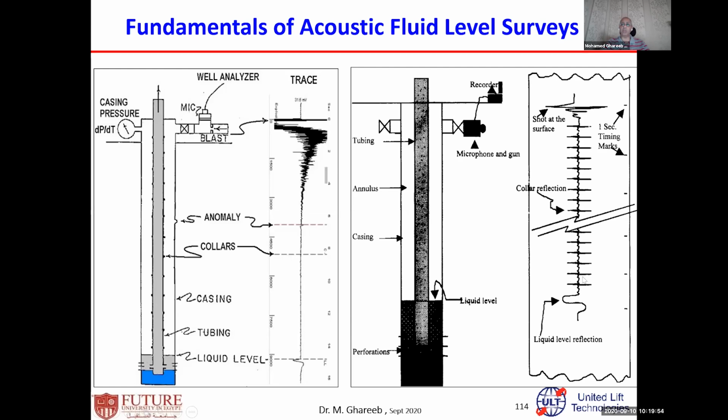Some other people say, okay, maybe I'm not able to measure this peak. Then you measure the sound velocity. When the sound is going down like this, it hits the level of the fluid, and the sound comes back to you again. If you measure the travel time of the sound going down, hitting the fluid and coming back again, and based on the sound velocity, then you know where your fluid level is.